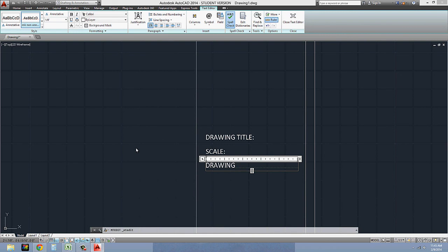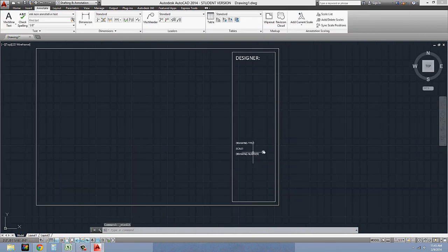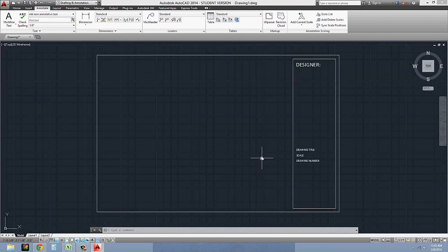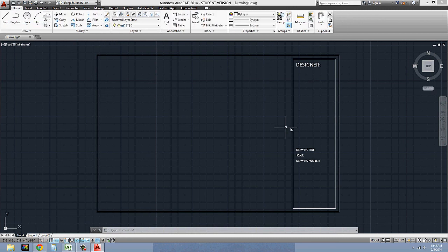let's say drawing number, and again, for the information to include on it, you can look to the example that I have for the title block online that I'll post on the LMS. And also you'll see, to reiterate, the layers that you need to assign these objects to. Right now they're all on layer 0, but we need to create our title block layers. Those are all in the LMS as well in the handout.